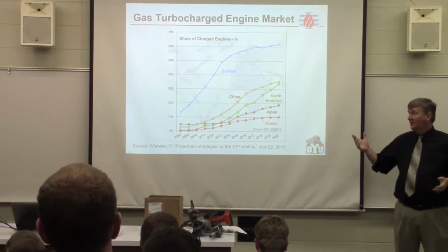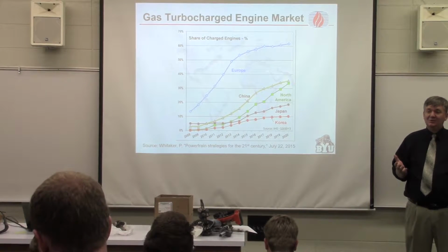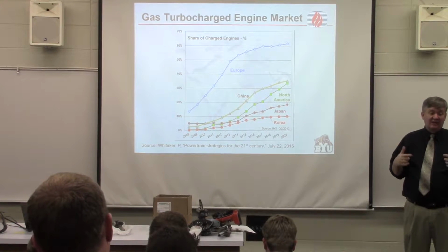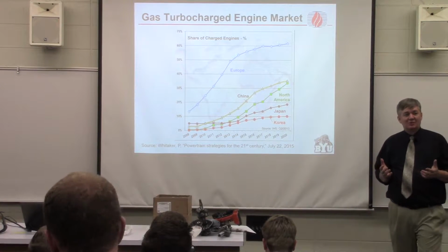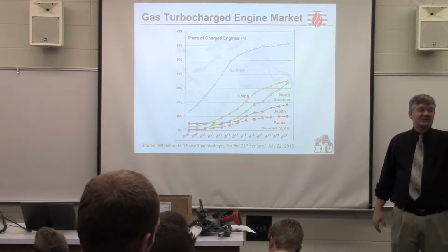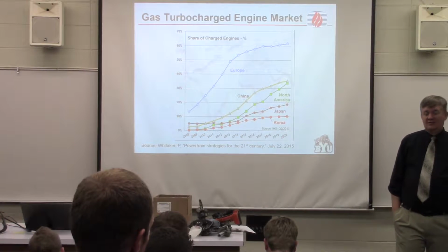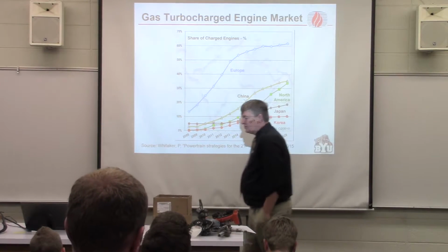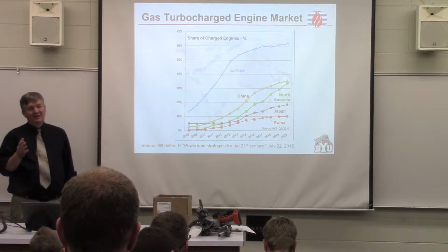Capital cost, and those turbines, if you build them cheaply, like a lot of people do, they spin at very high velocities, and maintenance on them can be pretty high. Replacing a turbocharger is a pretty major expense. I was gonna ask about the efficiency. Yeah, so you get a boost in efficiency, and an especially large boost in power, and a somewhat smaller boost in efficiency.